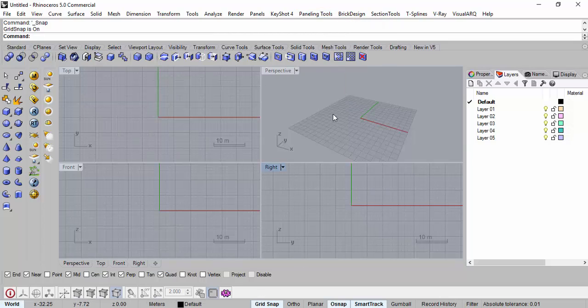Okay. So essentially when you open your software, you have these 4 viewports, and it shows you the units. You're working with meters here. Is it any different in yours? I will come to that. We'll look at the settings, how to set these to different units, millimeters and other things. And as you're moving the mouse, it shows X, Y, Z coordinates. So it's giving you real positions of your cursor in the space. And everything that you draw in these viewports is in 1:1 scale, in real scale, yeah.